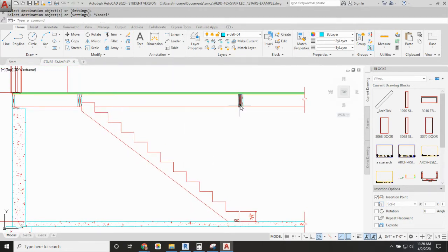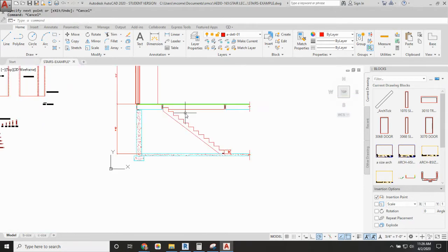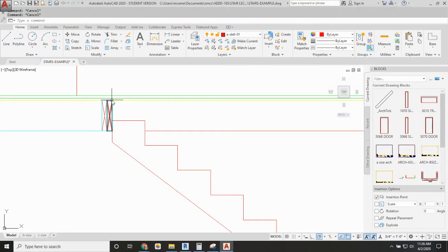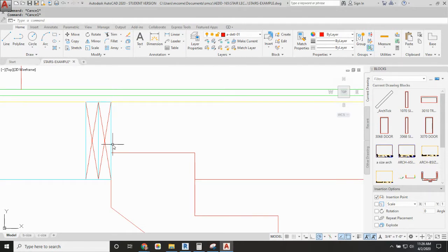Okay, so actually let's make this right. These line weights are important to get right. So this would be a thicker line because it would be in section. And then this would be a thicker line because it's in section. And then we'd have a thin line here. There we go, because that's beyond. And then between here and here, you'd have a bit of, let's go out 0.25 inches. Actually, not 0.25. Let's go out 1.25 inches.